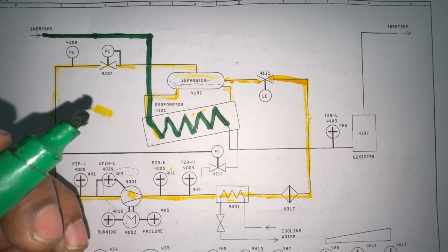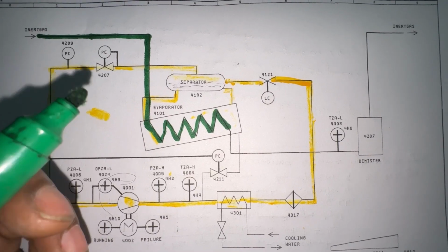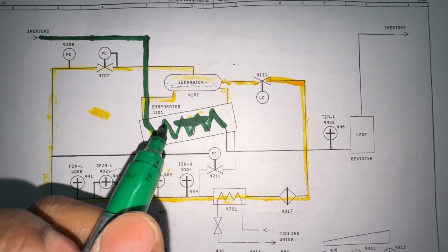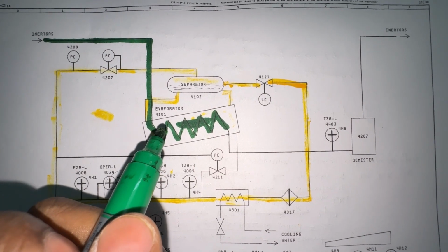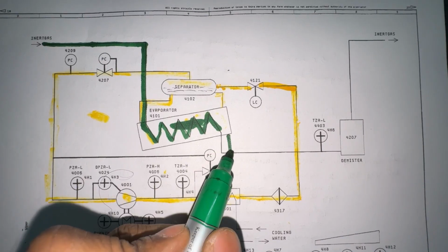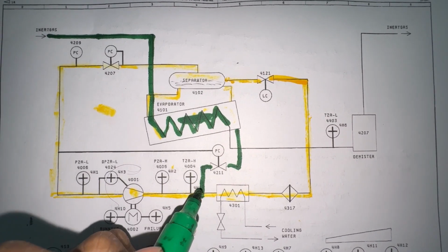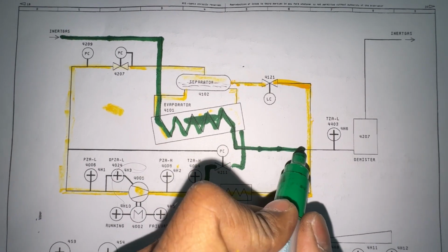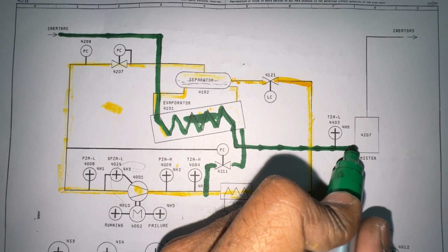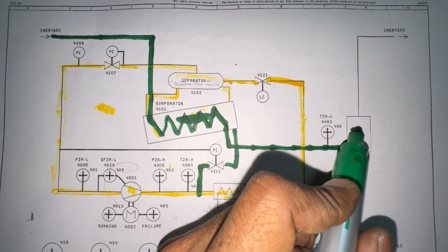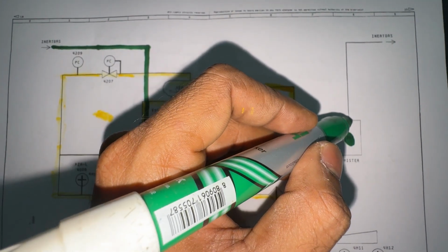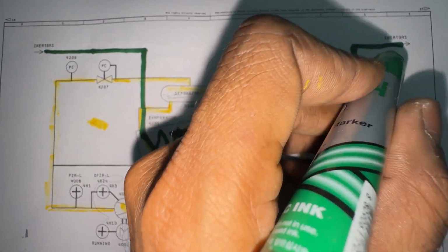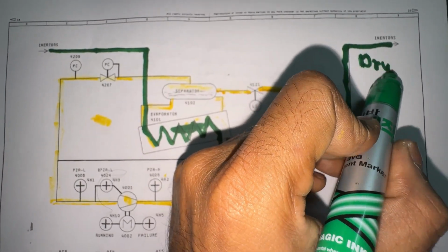This IG is clean and warm, having humidity, so here heat exchange takes place and maximum water is extracted from the IG, and this water is drained overboard, and then the cold IG is passed through the demister, where the remaining water is also removed and only cold IG is let pass, and this cold IG is then passed through the dryer.